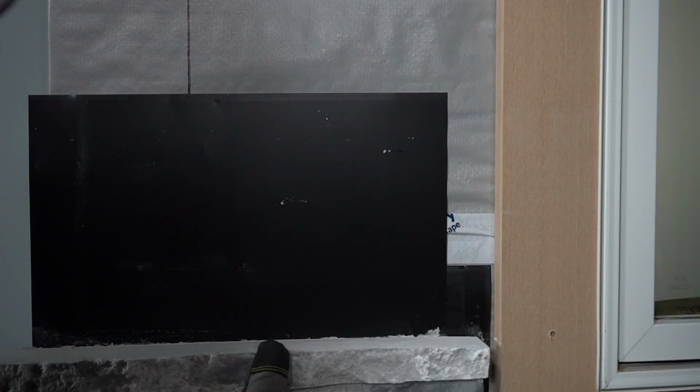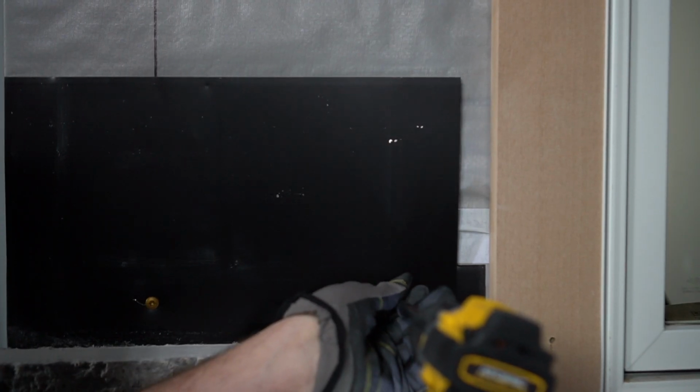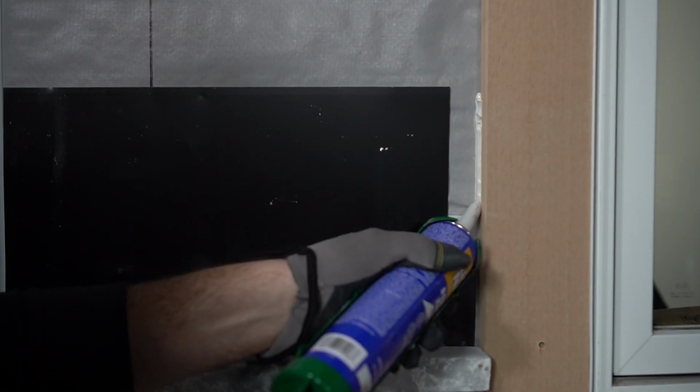Vertical transitions occur anywhere Silvermine Stone products meet another material's vertical edge. These edges must be flashed one course at a time. When the vertical transition occurs mid-wall, like a window, the flashing from the flats installed directly under the corners of the opening should be cut to fit tightly around the bottom and vertical edge of the opening. The seam must be sealed to do this.